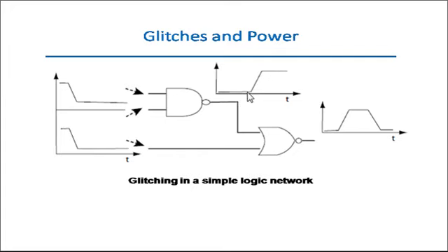Because of this, for this small period, both inputs to this NOR gate are 0 0, which causes the output to become 1 for the time period of the propagation delay of this gate. This is what we got in the output, a little high value.